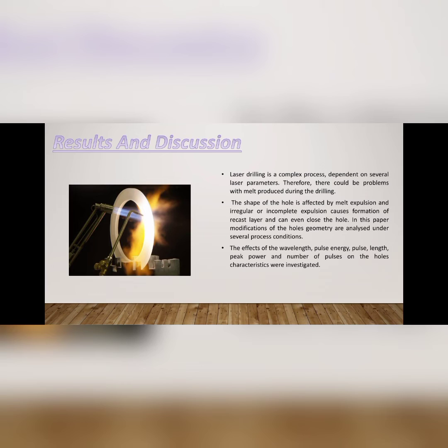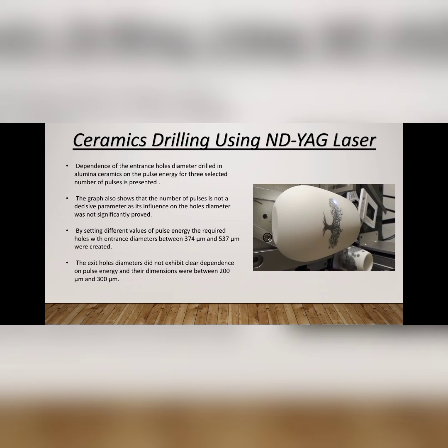Let us discuss this. Laser drilling is a complex process that depends on several laser parameters. Therefore, there can be a problem with the metal produced during drilling. The shape of holes is affected by melt ejection, and irregular or incomplete ejection causes formation of a recast layer and can be examined by geometrical analysis.